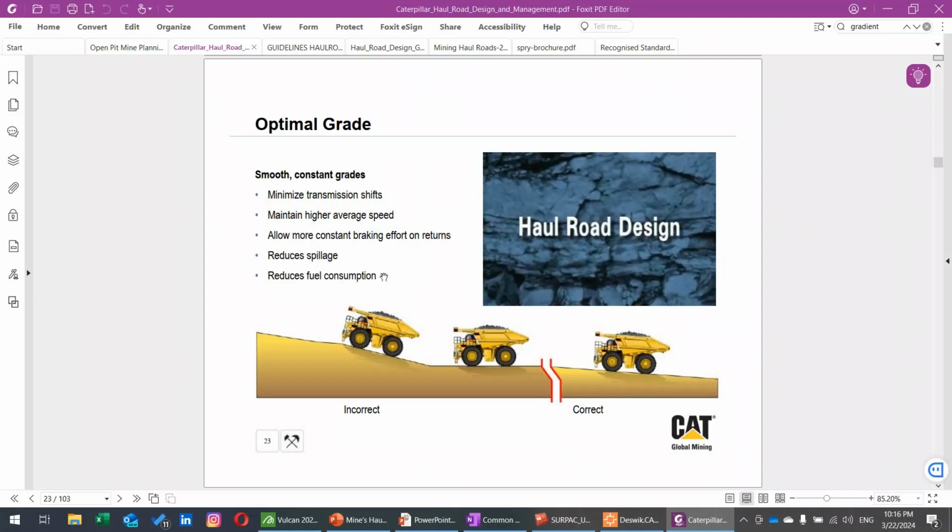In our next video, when we are analyzing a mine design, a pit design, we will see how this myth is being wrongly used when the design was being prepared to include a flat path, a flat profile, a flat length in the ramping system of pits, rather than those locations where we need a nearly flat connection of the bench entry, bench access to the ramp.